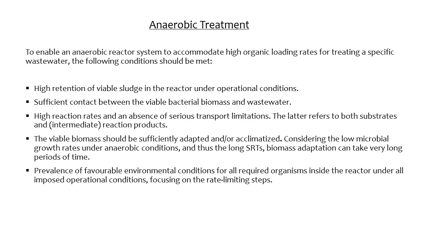The viable biomass should be sufficiently adapted and/or acclimatized. Considering the low microbial growth rates under anaerobic condition, thus long SRTs, biomass adaptation can take very long periods of time. Prevalence of favorable environmental conditions for all required organisms inside the reactor under all imposed operational conditions, focusing on the rate limiting steps, should be taken.